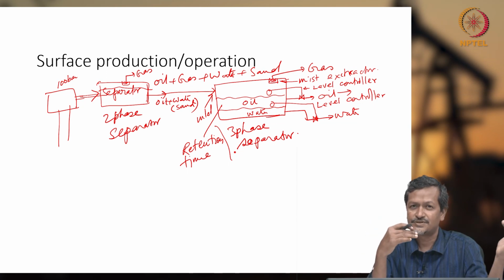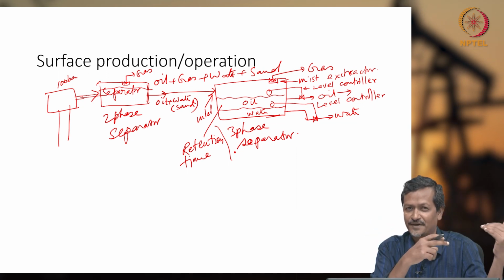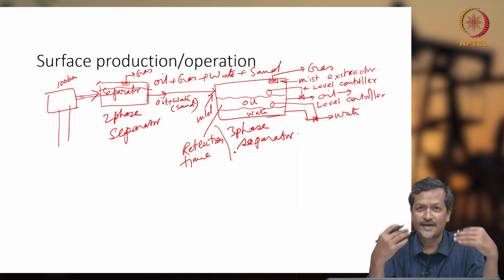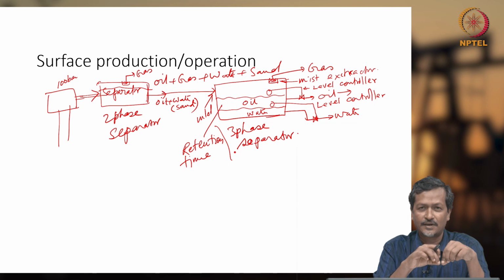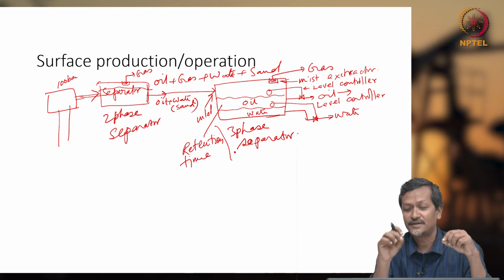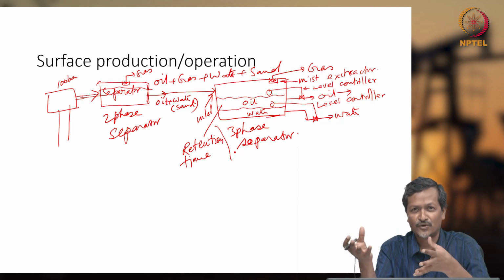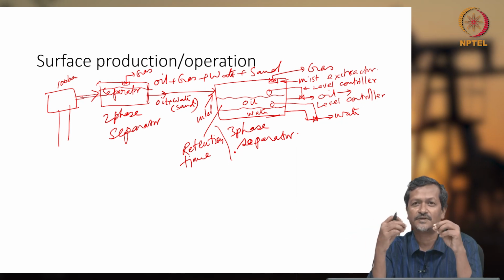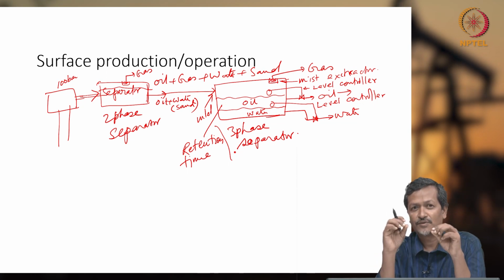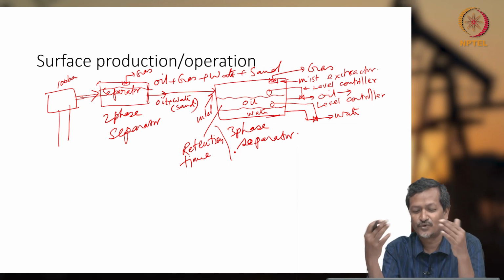And I was teaching the sand control part. If you are not controlling sand properly, then you will have lots of sand. That sand will get deposited into your separator system, so that will be blocking your flow path and eroding the surface. The separator system may not work because it has small valves and nozzles, and lots of bends and turns, and erosion and blocking will be there.